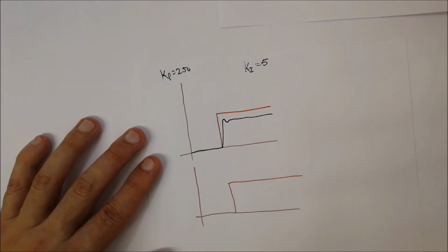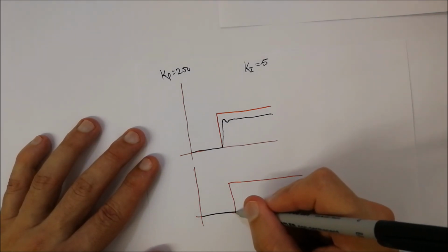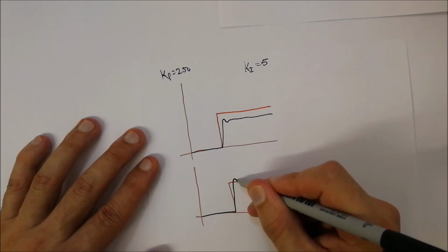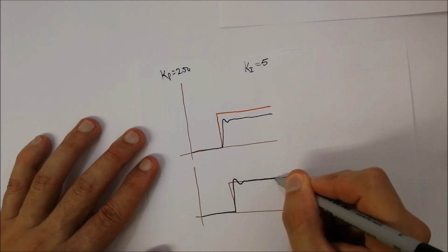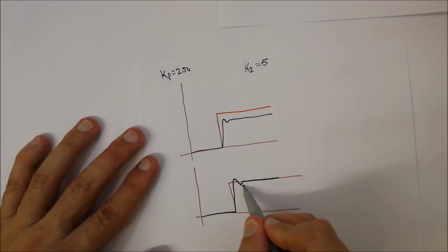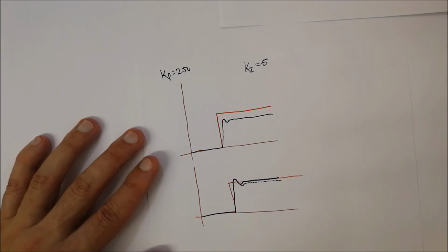You get up to the point where you ramp it and it goes up to the set point, oscillates maybe a little bit over there, and then it's equal to the set point. If you find that it's just below the set point, increase the value of the Ki until you get it exactly over there.